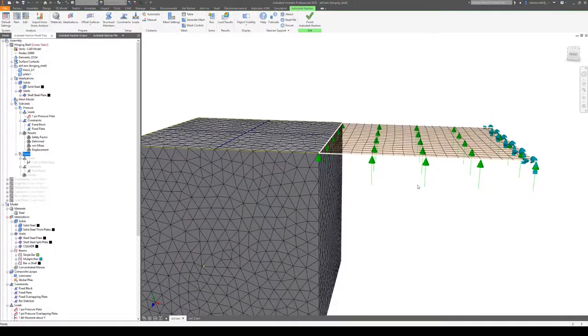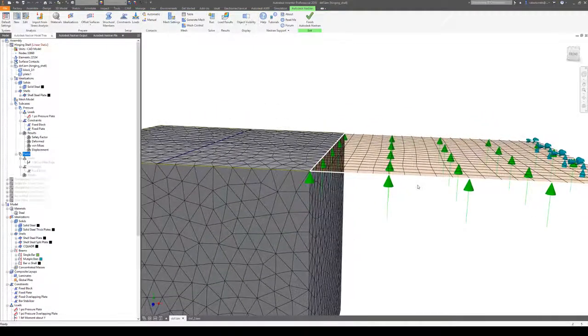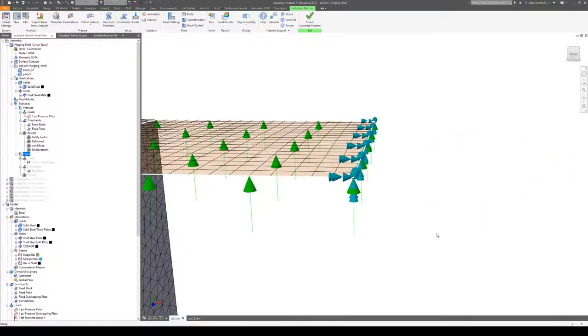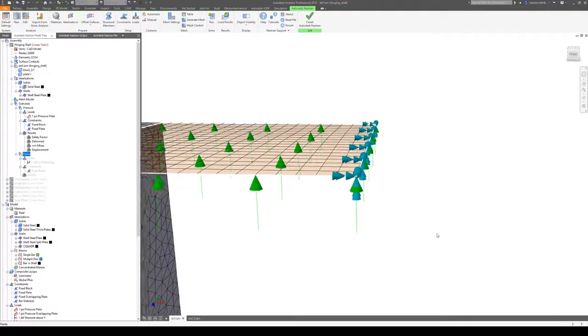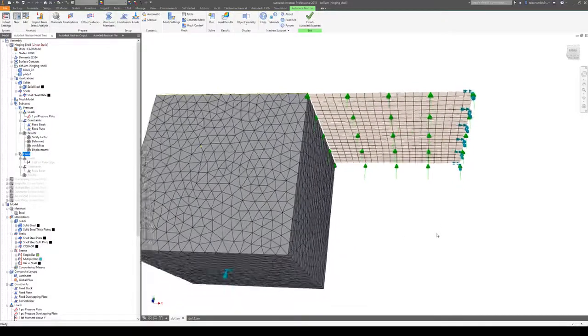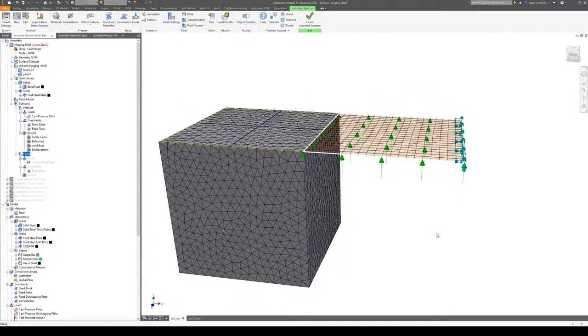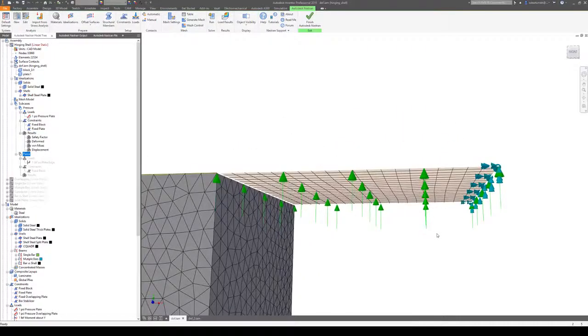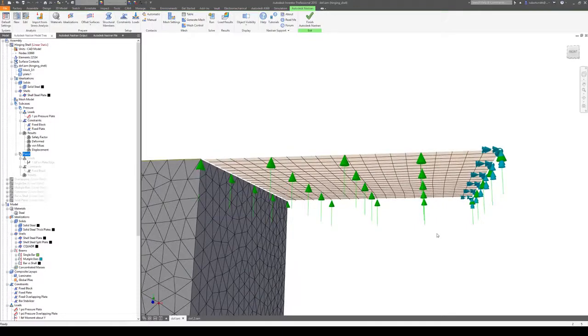They're still meshed in the same way. They're still joined together with a bonded contact. But this time I've put a fixed constraint on the end of the plate structure. So with a fixed condition on that part and a fixed condition on the solid block, no matter what, I know I'm going to get a static problem, but it still may not behave exactly like I expect it to. This time I've applied a pressure to the underside of that plate structure, just a uniform 1 psi pressure.